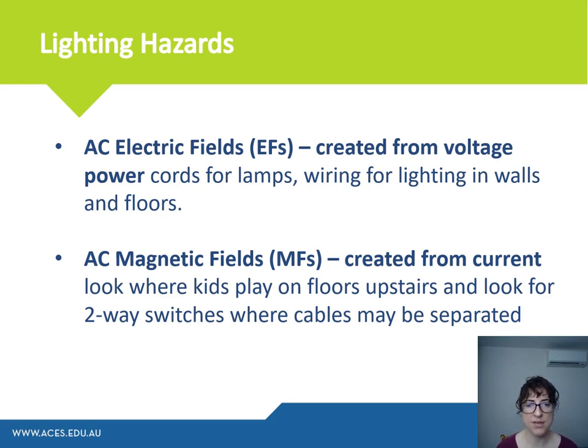The other hazard that comes along with two-way switches is high magnetic fields as well, because the active and neutral can be separated, and that can create a high magnetic field throughout that whole room. So when you're looking at the plans, you really need to make sure that the active and neutral stay together, and that if you do have the two-way switches, they're wired correctly so that those are together on both sides.